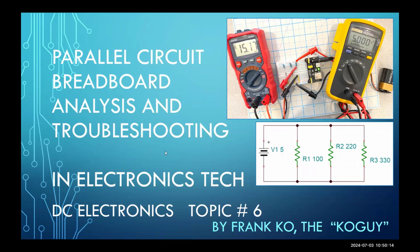So in this title page, you'll see I've got 2 multimeters on a parallel circuit, and I'm measuring current and voltage simultaneously. The circuit that we're going to be using is shown in the drawing of the cover sheet. I've got 3 resistors in parallel with each other. We will define how you recognize parallel components. And so I've got 3 resistors in parallel with each other with a 5-volt source. Let's go ahead with the next.